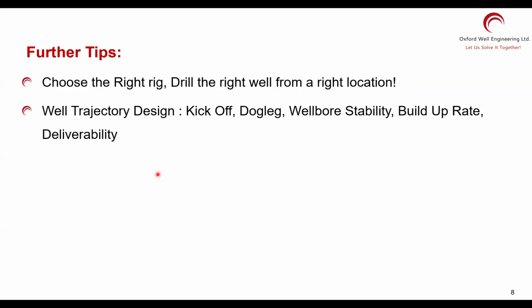Well trajectory, kickoff, dog legs, and everything else you need to get right. And the casing wear, people say the contact forces. Most people don't have casing wear software, so they say, give me the contact forces. Contact forces are the indicator for that. If you have high contact forces, and when I say high, there is a number on it that we need to watch for, we can multiply and estimate the casing wear if you don't have fancy software. I use the fancy software; it's worth the time. Sometimes the casing wear can eat up very nice casing structures.